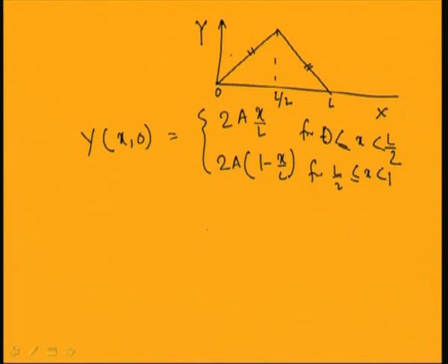So, in this case, with this initial condition you have to find the resulting vibration of this string. So, this is the expression for this displacement. You require another initial condition also, let the velocity, that is del y by del t at t equal to 0, equal 0. So, let you have given an initial displacement and no initial velocity to the string and let it go. So, at t equal to 0, velocity equal to 0. With this you can find the solution of this system.